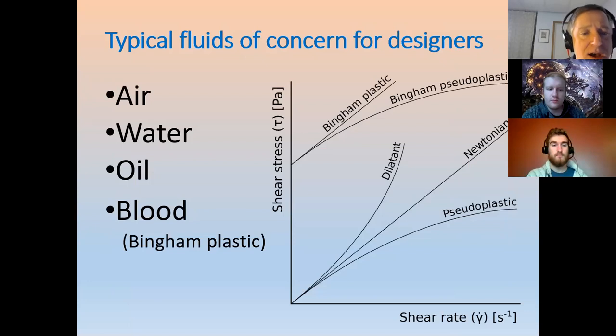Okay, rheology. The first question you ask when you're dealing with a fluid dynamics problem, which includes convective heat transfer, by the way, is what are the rheological properties of the fluid? Basically you're asking is it Newtonian or non-Newtonian, and then you ask about viscosity, specific heat and all these kinds of things. Rheology means these properties that we think we know change with pump speed or shear rate. That's unusual. With molasses and paint and things like that, the rules change.